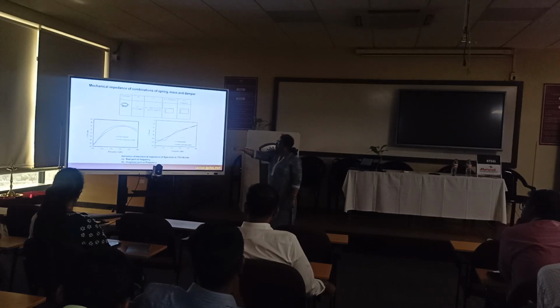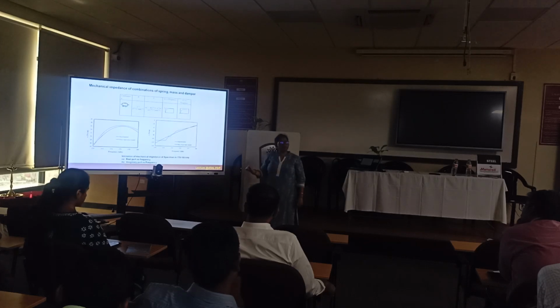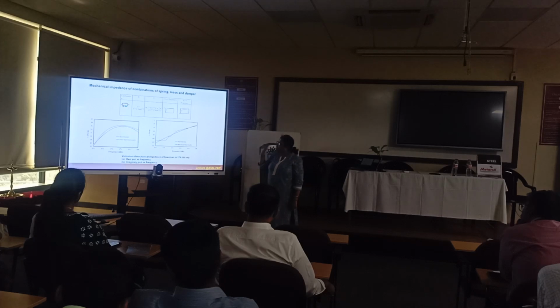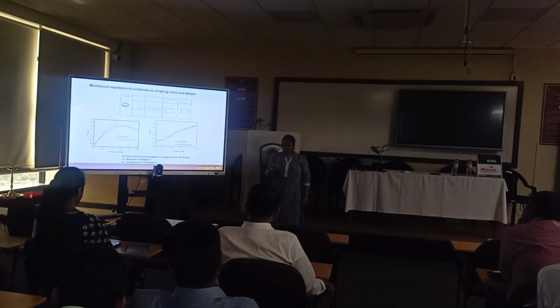So from these two curves, can I have multiple x0, x1, x2, y0, y1, y2 with the corresponding frequencies omega 0, omega 1, omega 2? Can I have a lot of equations, solve them and get the MCK value for a particular range? And this gives you the result based on the spring mass damper system, to understand what kind of dynamic model it is.